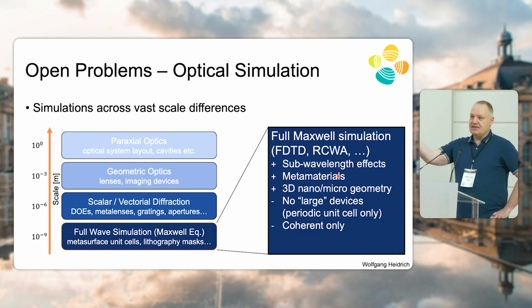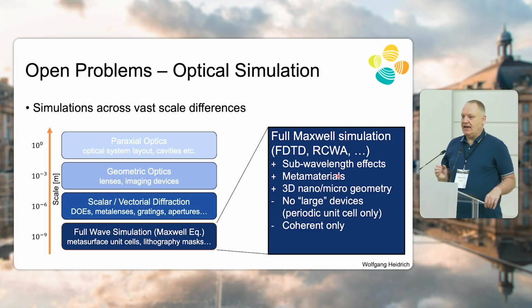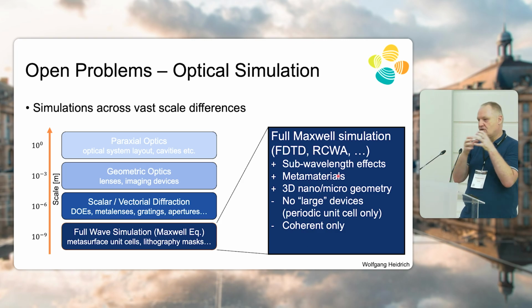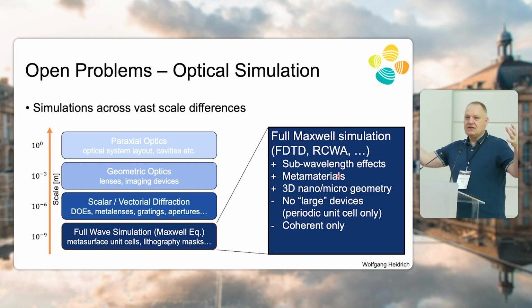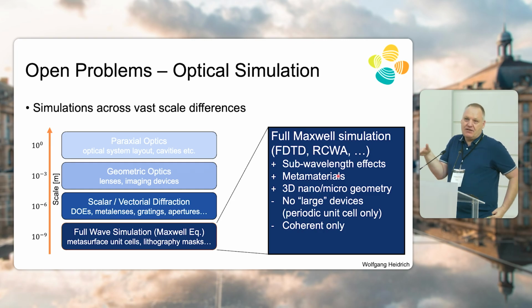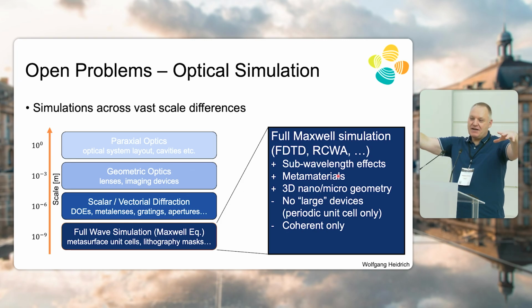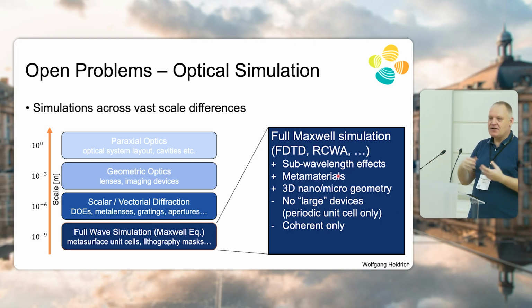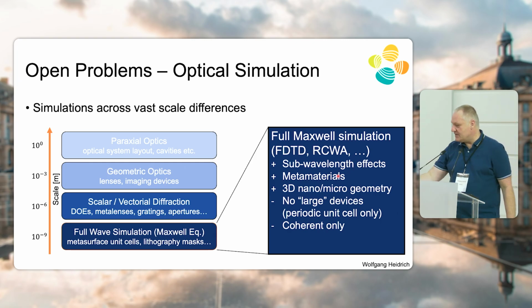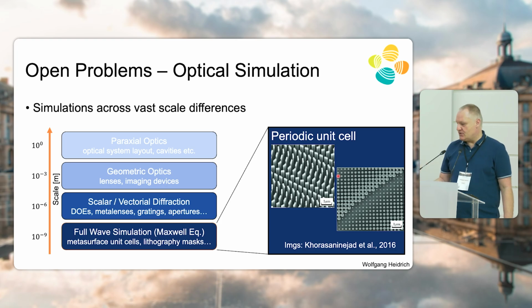They're basically discretizing the space into sub-wavelength unit cells, and what that means is that you can really simulate only very, very small domains. So it's really limited in simulating large-scale devices. But it's done for meta surfaces. The way we design meta surfaces is, for a meta lens, theoretically you could build whatever you want over your 1 centimeter or 5 centimeter or whatever aperture. But in order to keep the computation feasible, we're breaking things down into unit cells.